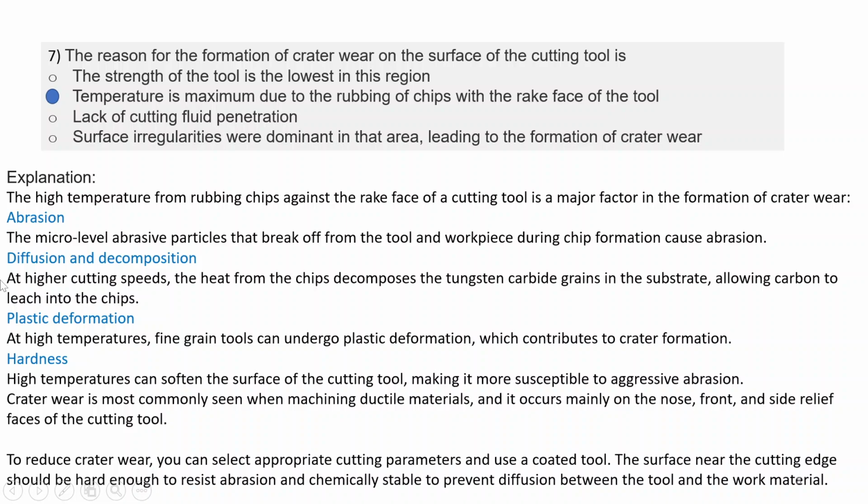Next is diffusion and decomposition. At higher cutting speeds, the heat from the chips decomposes the tungsten carbide grains in the substrate, allowing carbon to leach into the chips. Or plastic deformation: at high temperatures, fine grained tools can undergo plastic deformation, which contributes to crater formation.